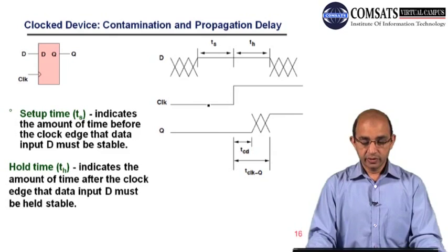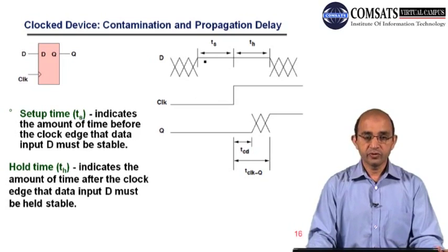So the data must be present at the input this much amount of time before the active clock edge arrives. We have to make sure that the data is present at the input of the flip-flop this much time before the active clock edge arrives.